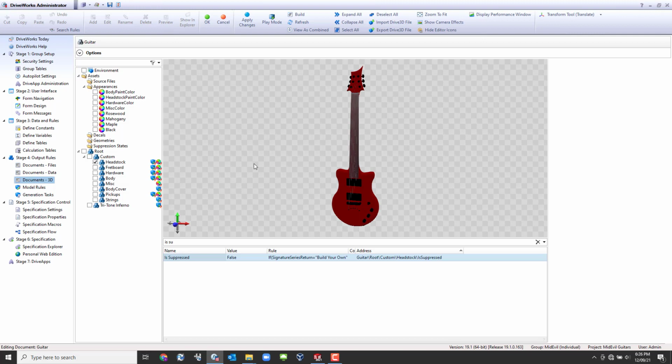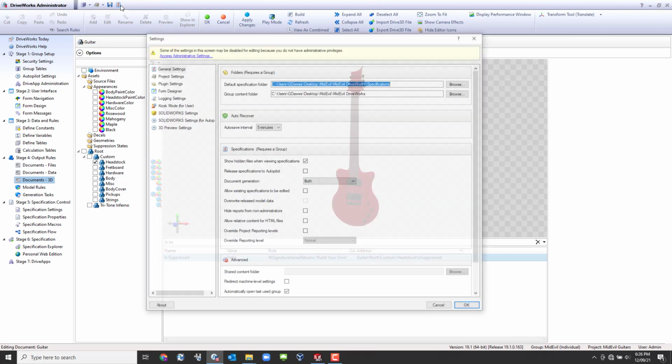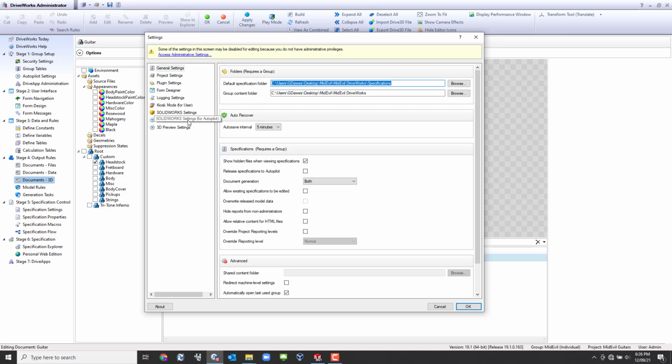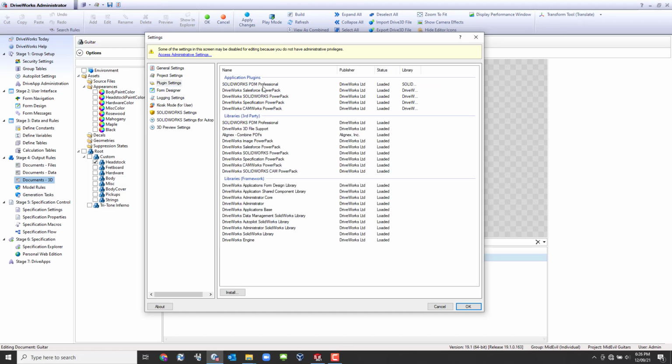There's some additional automation that can be used with this, DriveWorks Autopilot. And this is also PDM compatible, so we can not only generate these models and dump them out to the network drive, it can actually push them out to PDM, check them in, and notify people that that is there, right? It can build spec sheets in the background for things.